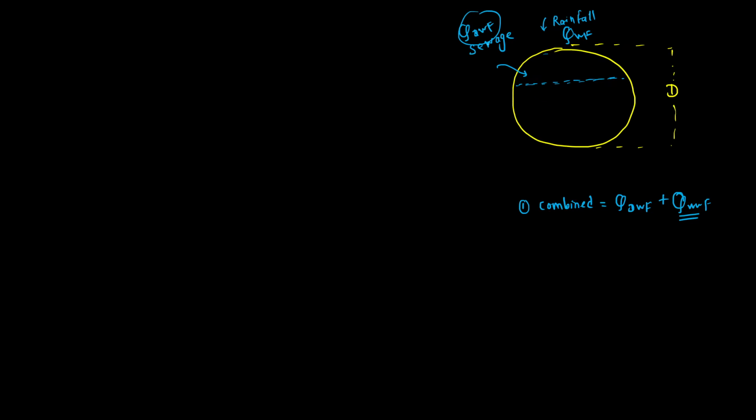So if the sewage is flowing at full capacity and then there is excess rainfall, what will happen? The capacity will be breached and there will be overflow of this sewage. To take that into consideration, we generally don't allow the sewage to run in a full condition, that is, we keep it at half or partially full condition.